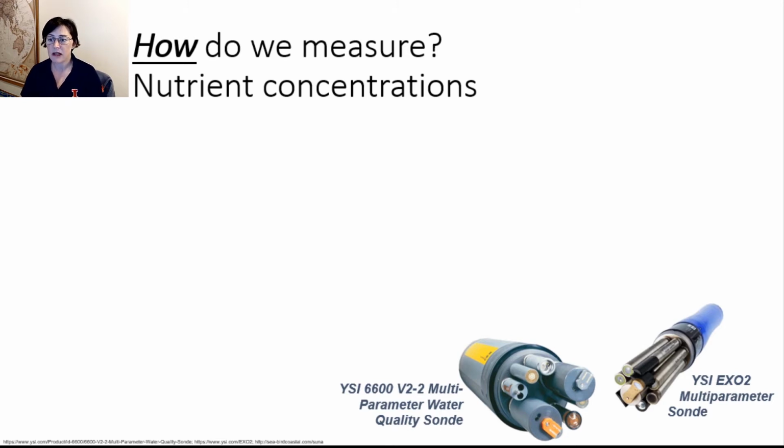At the bottom of the screen, you see YSI handheld sondes. You basically stick these sondes into the water body that you're interested in or into a bucket of your tile drainage water that you've collected, and they read out a nitrate concentration. So there is no sample collection involved if you use those water quality sondes. The challenge with these, though, is that people often don't realize the calibration burden. These sondes have to be calibrated every couple hours if you're using them over the course of like a day. They definitely need to be calibrated every time you go out.